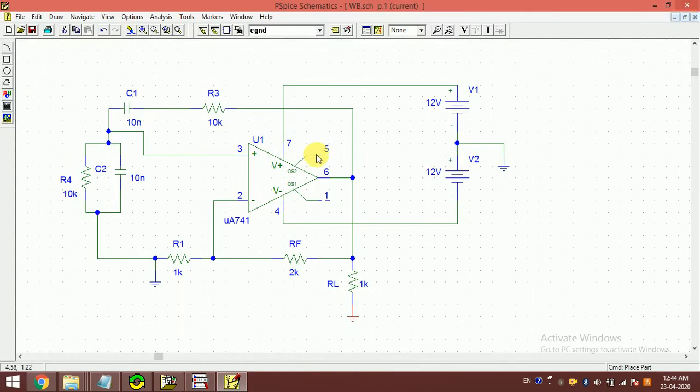Now see, an oscillator circuit is not so easy. An oscillator circuit is slightly complex compared to other circuits. Now see, here it is 10 kilo ohm. If you look only at the resistor part, this is 10 kilo ohm, and this capacitor will also have some capacitive reactance, and this is a very low resistance part. So most of the feedback current will flow through this part.